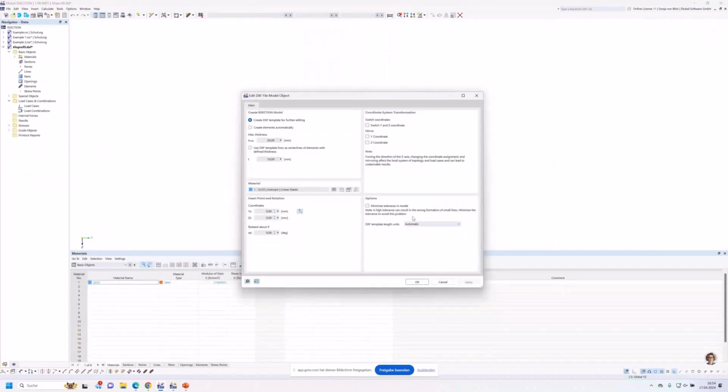In section Create Section Model here, you have three options for creating the cross-section. The automatic creation of elements is useful if the outlines of the cross-section are available in the DXF file. Our section attempts to create center lines for parallel lines and then set the elements between the intersections. Only elements that do not exceed the maximum thickness that you can define here are created.